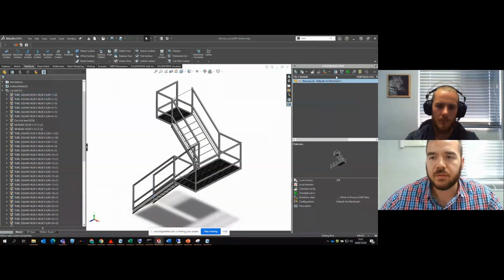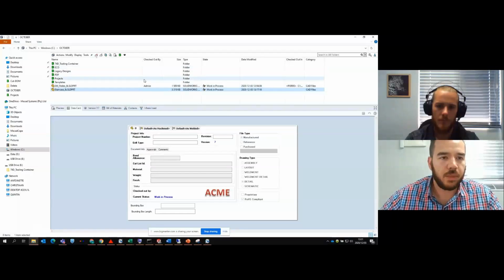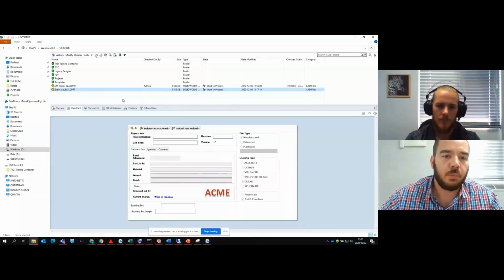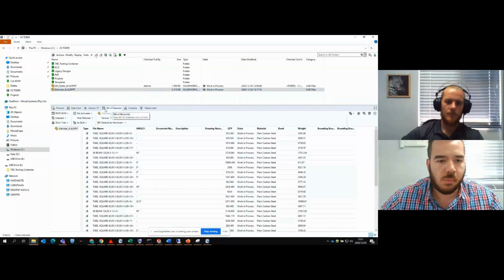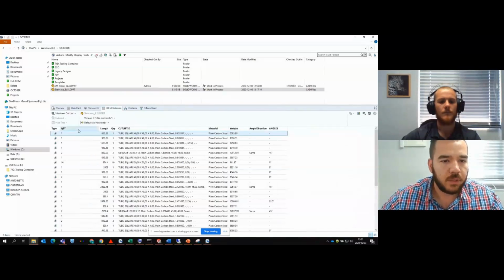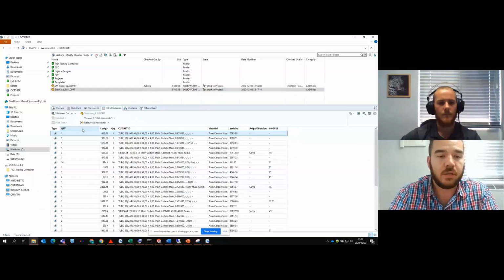If we look at this file now in our PDM vault, from the get-go, you'll see that your data card still looks empty. But remember, these are custom properties for the part, whereas the Cutlist items are Cutlist properties within our parts. But if I go over to my bill of materials, I will have my options, and if I select my Weldment Cutlist, you will now notice that for that one part, I've got all of the important properties currently assigned to it.